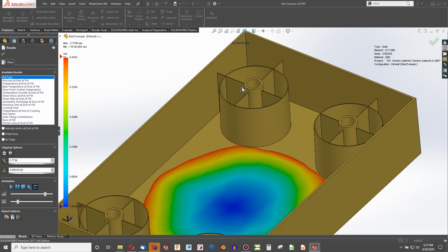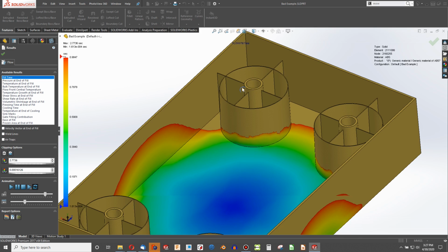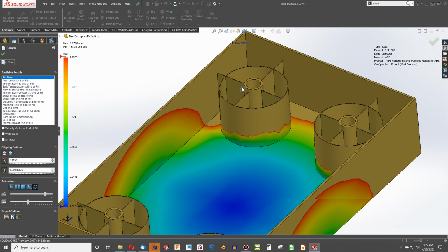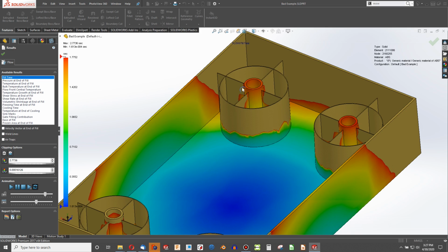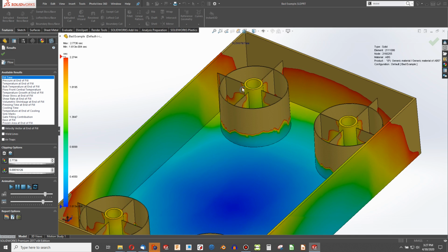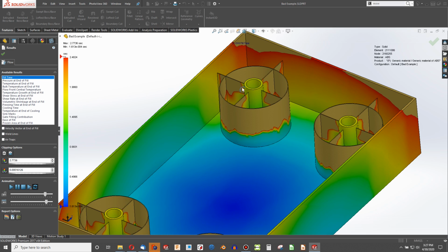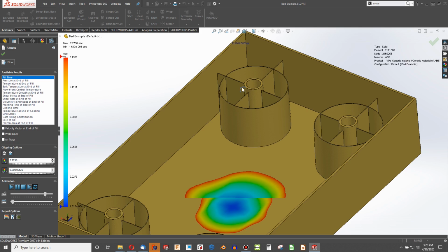Nonetheless, people break the rules all the time and are successful, but keep in mind that there are different compromises you have to make, whether it be the quality of the fill, the ejection, the warp afterwards, the sinks, voids, lots of things to consider, so be very careful when deviating from an ideal design.